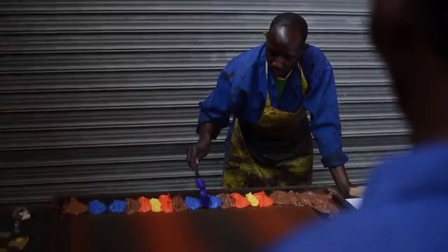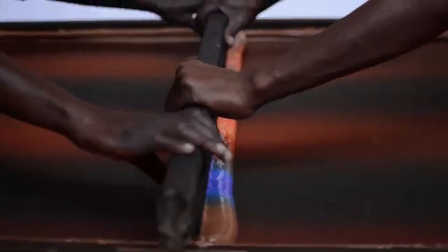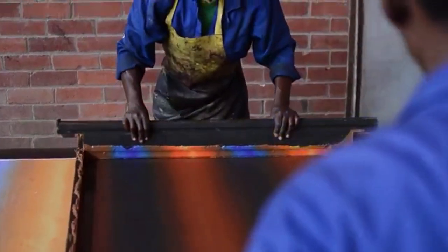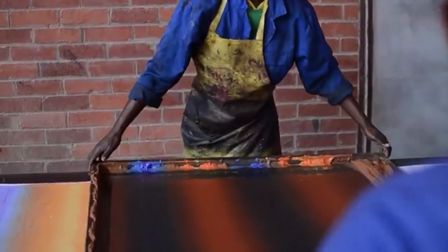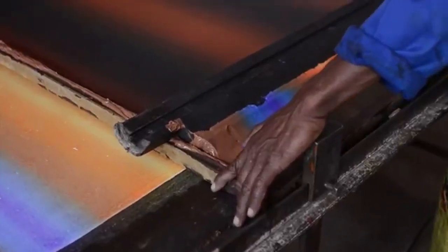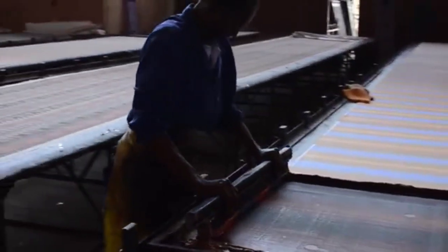Here they are putting the printing ink on the screen. Now, one thing about this particular video is that they are putting inks of different colors because they are producing a particular type of fabric. However, usually in printing, only a single color is printed from a single screen. So they lift the screen and then they put the screen on the next unprinted patch of the fabric. And they have to position it very carefully. Otherwise, of course, the printing will not be done exactly where we require it on the fabric.